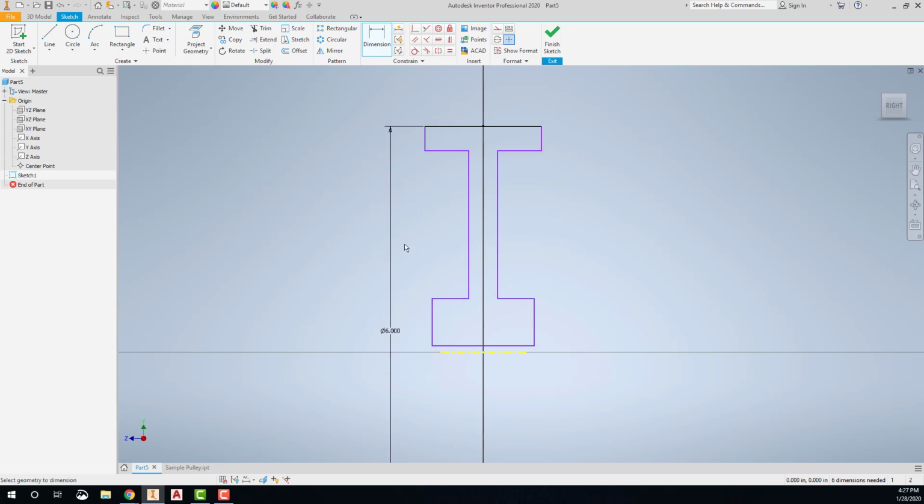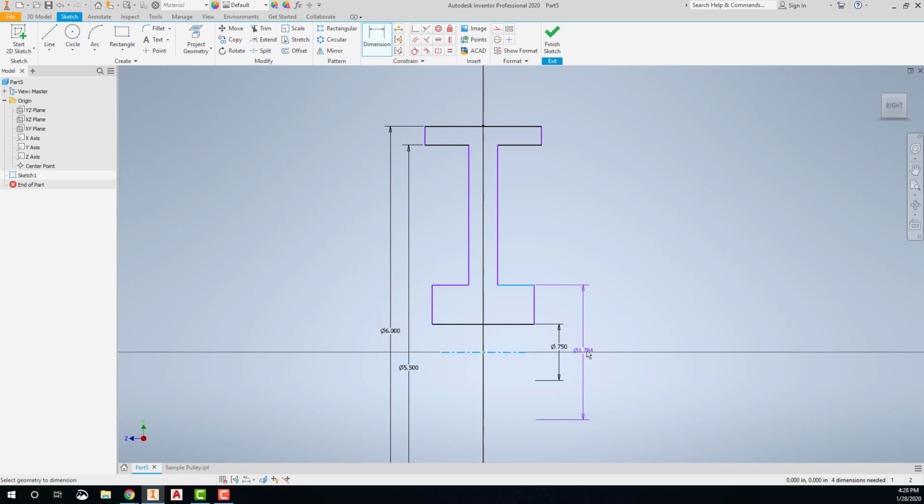And then if I need to, I can kind of readjust my geometry a little bit so that it's not going to jam it up at all. Okay, this one here is going to be 5.5. The middle one has a 3/4 inch diameter, and the outer one has a diameter of 2. And then it's just from here a couple more dimensions. That's going to be 1.5. This is going to be 1/4, 0.25. And then this one is 1.25.